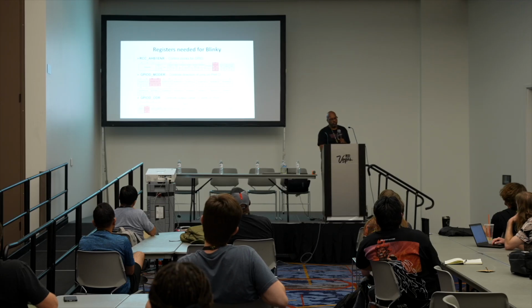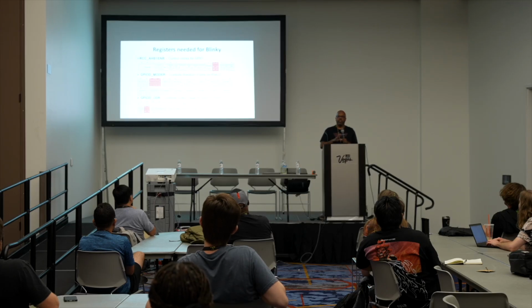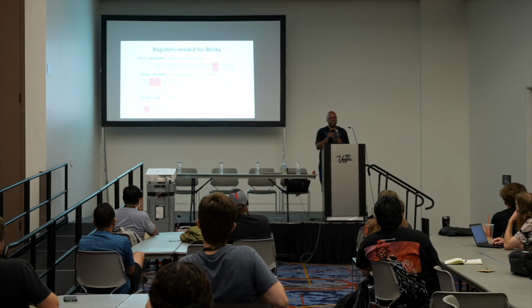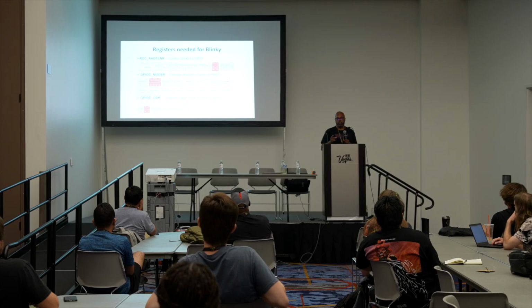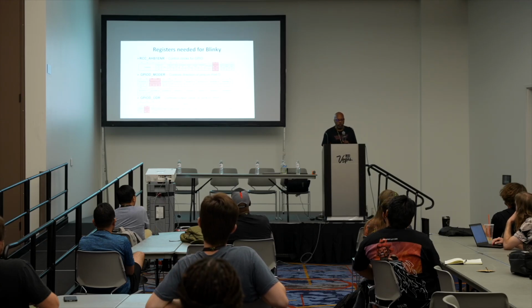So, okay, now I'm just showing you a few of the registers just to intimidate you, to make you see this data sheet is pain. I don't expect you to understand all this, but when you look in the data sheet, it has a description of every register. And I just zoomed into a piece of that. So there's this register, RCC. AHB is a bus name. This controls the clocks for the GPIO pins. So I have to turn the clock on for a particular port.